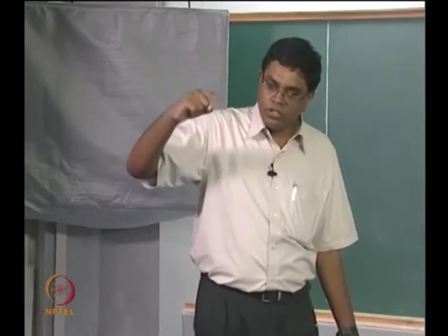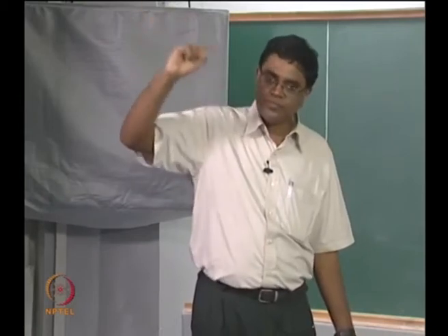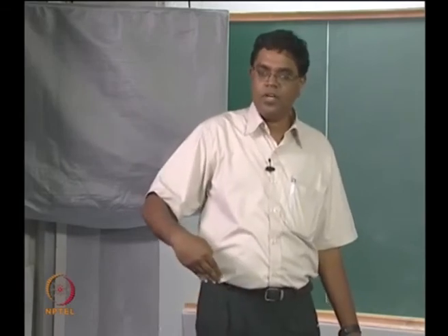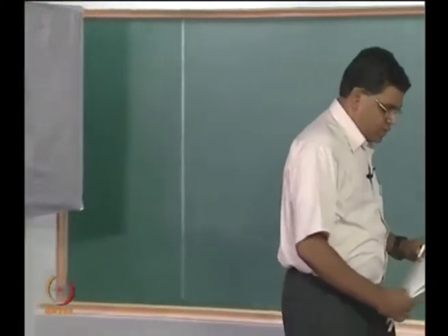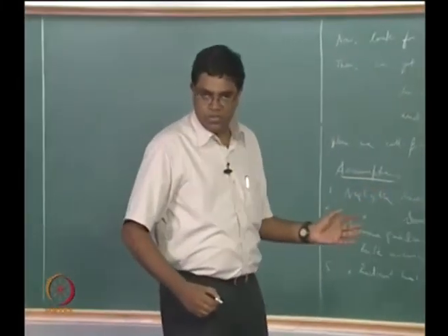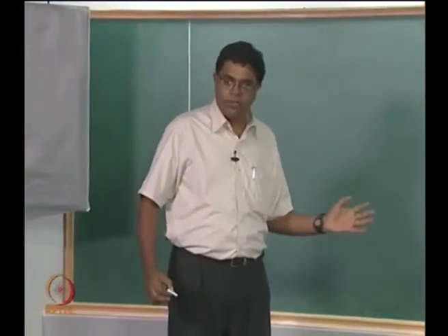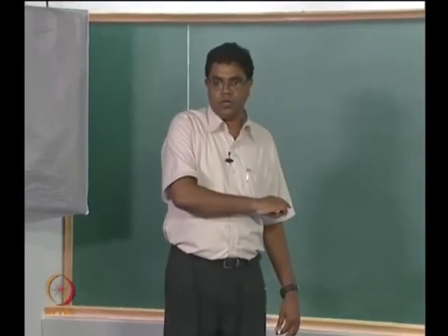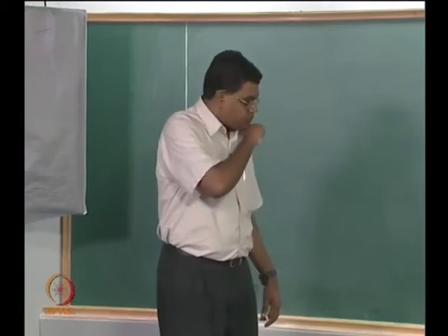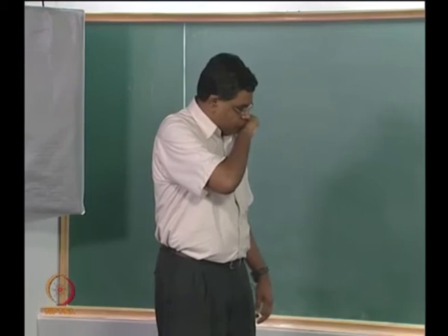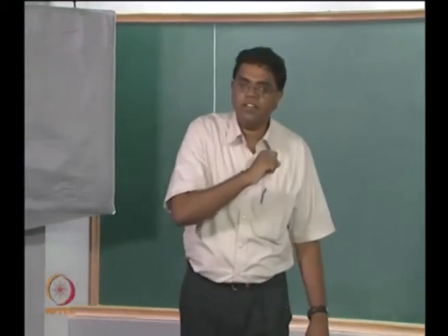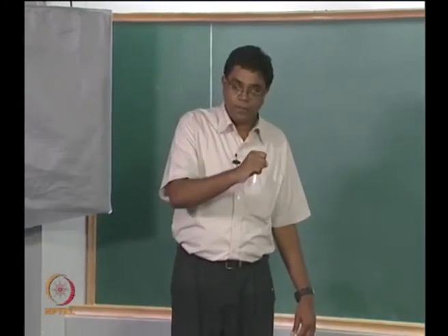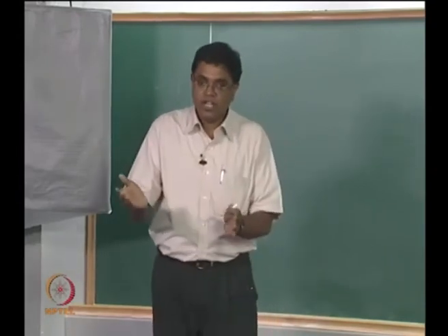There you try to couple that equation with the energy equation, where the Lewis number of that particular species is equal to 1, but you keep the other one. So typically, in the problems that we deal with, let's say we will want to do a premixed flame or a diffusion flame and so on in due course, our starting point will be the Schwab-Zeldovich formulation. At that time we should look forward to seeing if we can relax the Lewis number unity assumption for some of the species, or say equal Lewis numbers but not necessarily equal to 1 and so on.